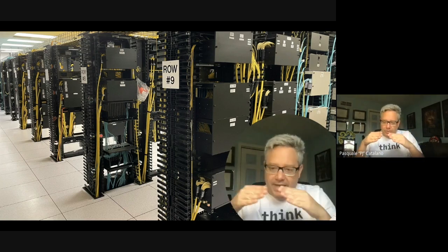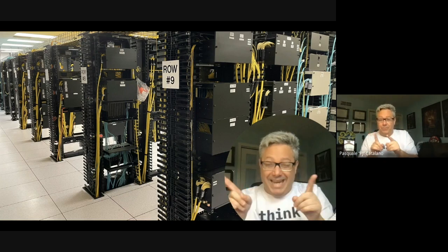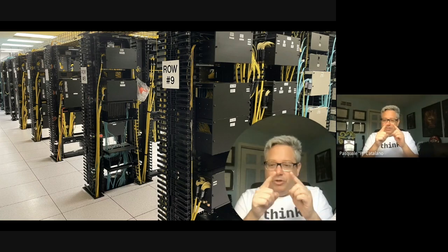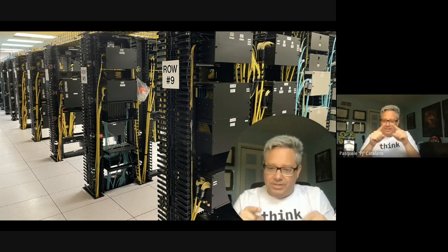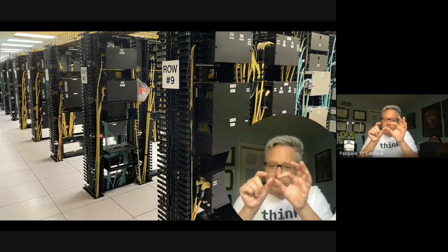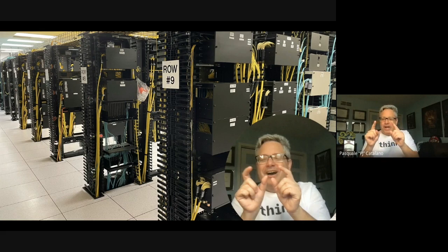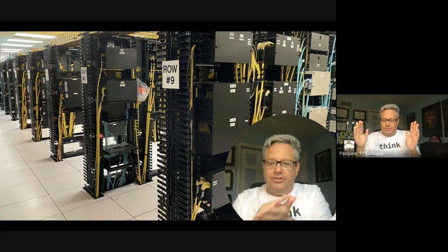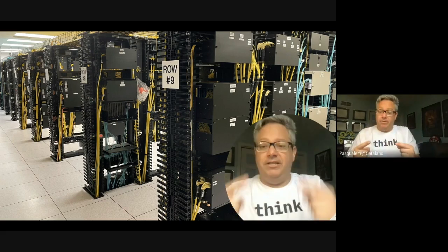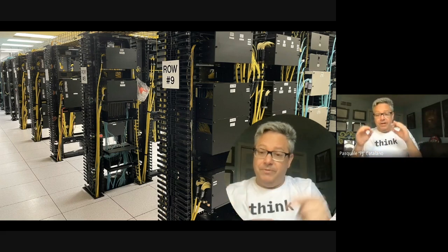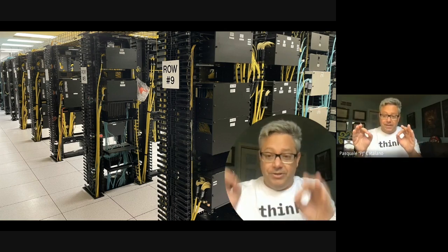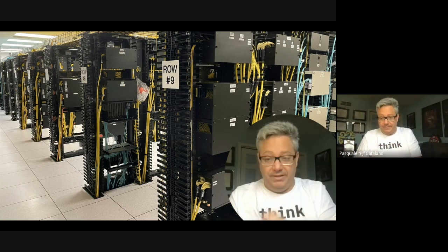But because you're getting more rays of light, more modes of light, into the fiber, you're going to get multiple pulses that represent a bit. And then as they travel, the pulses will spread out and shrink. So the transmission length will decrease on a multi-mode. Every time I double the speed on a multi-mode cable, so if I go from 16 gigabit per second Fibre Channel to 32 gigabit per second, I can only go half the distance.